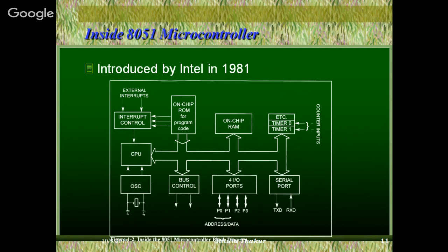And this is another important difference between a microprocessor and a microcontroller. In case of a microprocessor, whatever frequency you want to work with, it will internally divide it by 2. For example, if you want to work at 3 megahertz, you will have to give a 6 megahertz frequency crystal, so it will automatically divide it by half. Whereas in case of a microcontroller, at whatever frequency you want it to work, you will connect a crystal of the same frequency. A microcontroller can work from a frequency range of 4 megahertz to 30 megahertz, but the most widely used frequency is